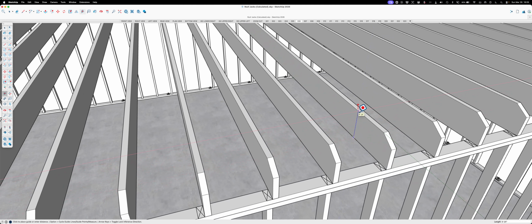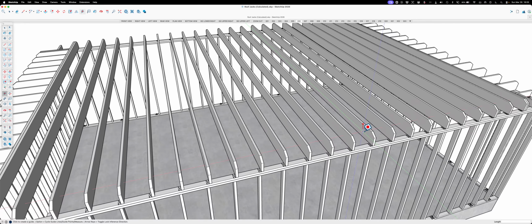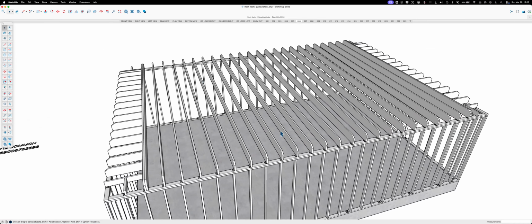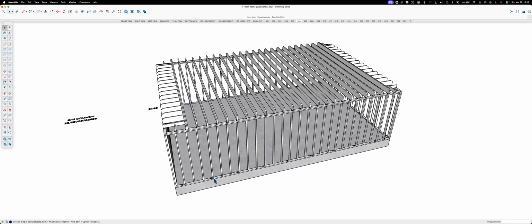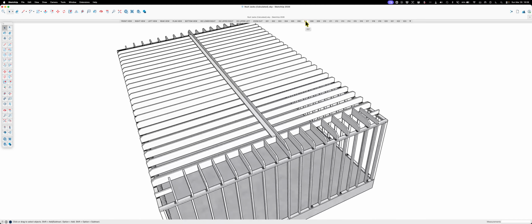So look down in this bottom corner down here. It says 9 1/4. Wow, and it just popped up on the screen too. So yeah, these are 2 by 10, but they're overspanned. There's no way they're going to go 24 feet. But this is just for showing you how to put it together. Always follow the codes. The prescriptive code, especially in the IRC, will give you a lot of this information based off lumber species.